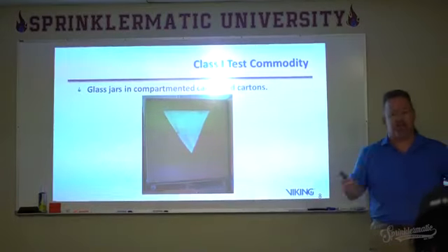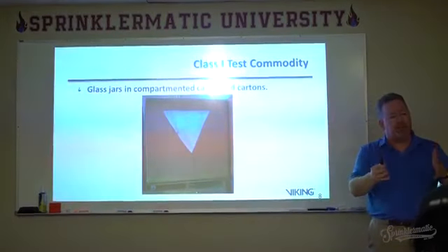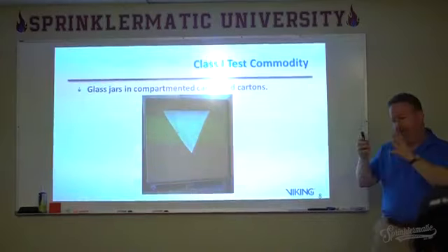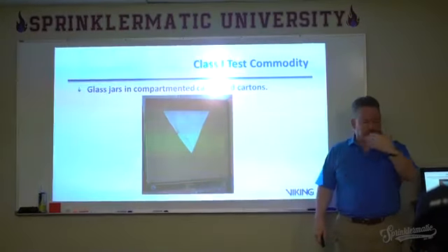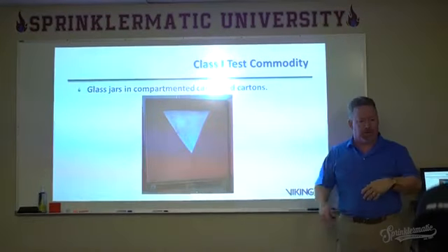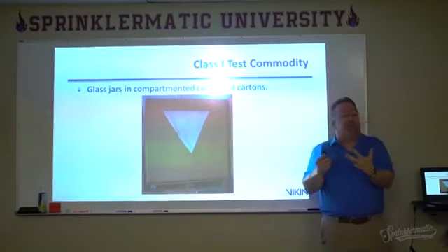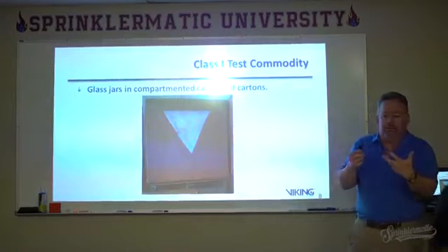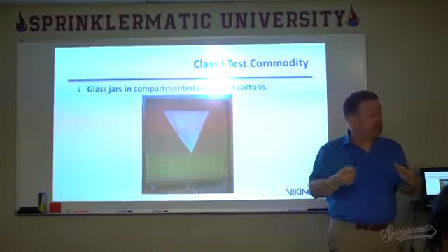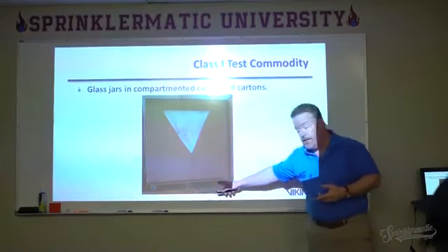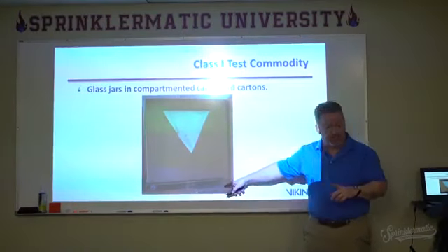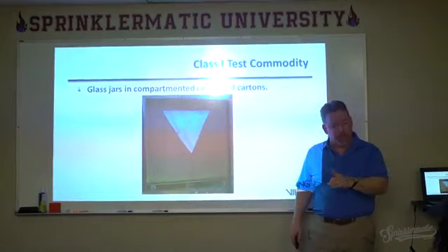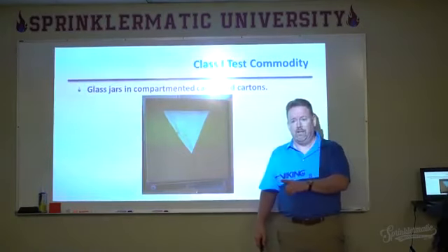Burn that commodity, determine its heat release rate, and use that as the test commodity to compare these other commodities to. So it's non-combustible in a single corrugated box. By definition, the single layer corrugated box was going to be the biggest challenge. And all of these were placed, when they were tested, on solid wood pallets.